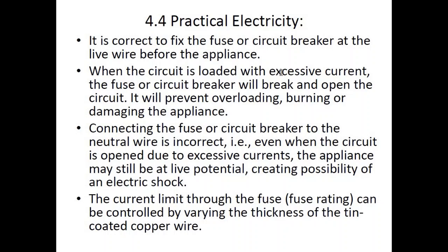Connecting the fuse or circuit breaker to the neutral wire is incorrect. This would not save your appliance from being burned out, because then the excessive current would be able to pass through your appliance and then it would reach the fuse or the circuit breaker. The circuit breaker or fuse would still trip or cut off the current, but by that time it would be too late. Your costly appliance would be a pile of ash, or you would have already gotten an electric shock by then.